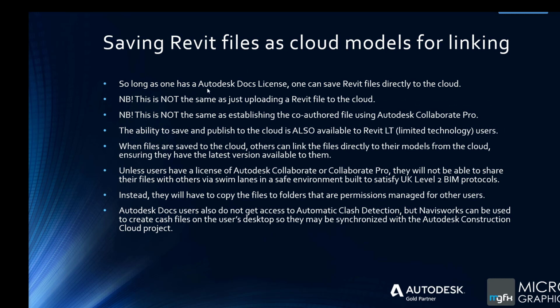Right, and then just with regards to Revit or Revit LT, if you have an Autodesk Docs license, you have to have a Docs license, then you can save a Revit file directly to the cloud. What does that mean? It's different from just uploading a file to the cloud, and it is also different to establishing a shared or a worksshared file on the cloud.